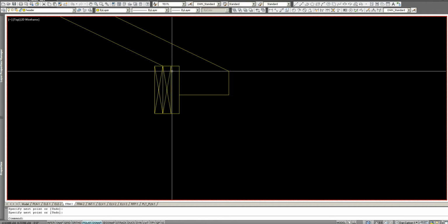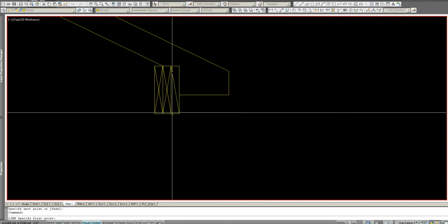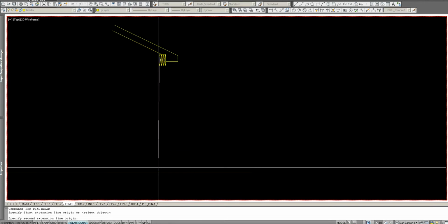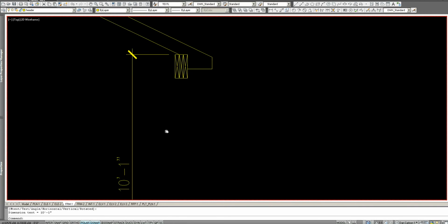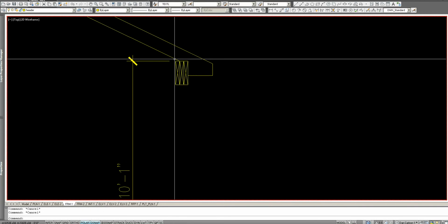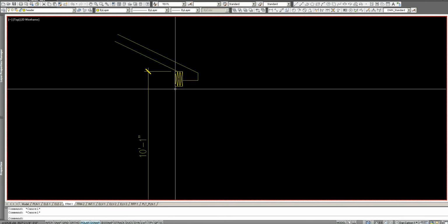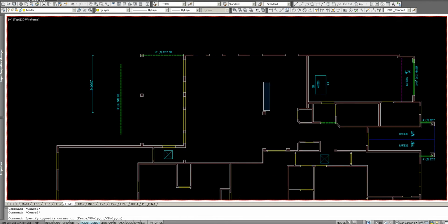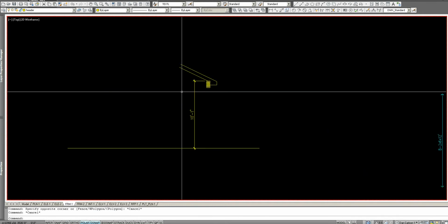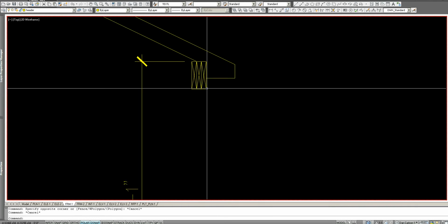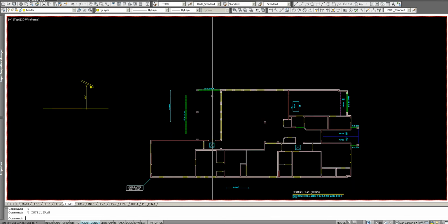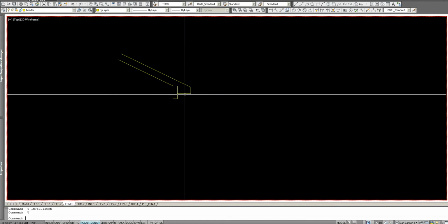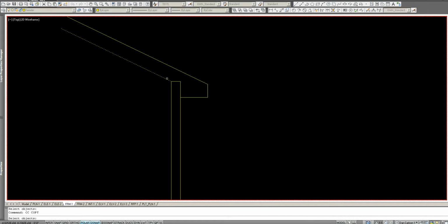So the reason it's a drop beam is because when we have a 10-foot 1-inch wall, it's measured to the top of the beam. So this beam is dropped. See how it's dropped from 10 foot down. A flush beam is what we will do inside the house right here in a minute. And the way that looks is, again, when we have our wall, just undoing everything. There's our wall again. Put our top plate on.